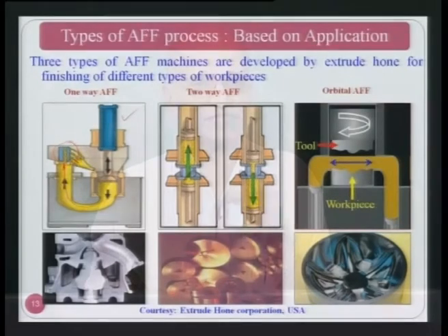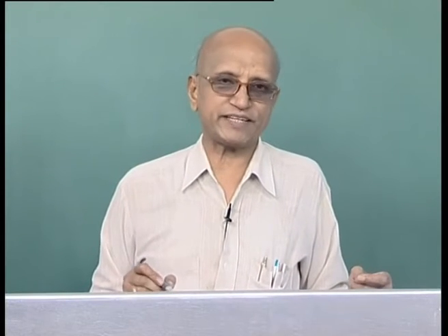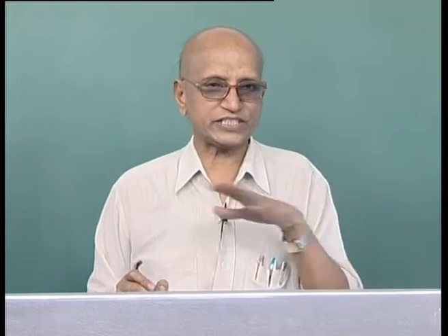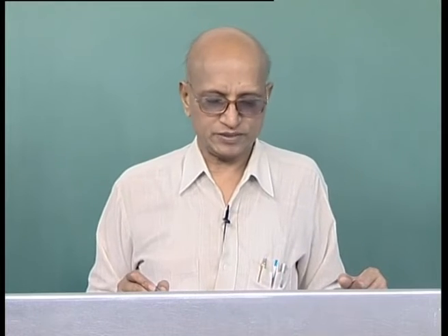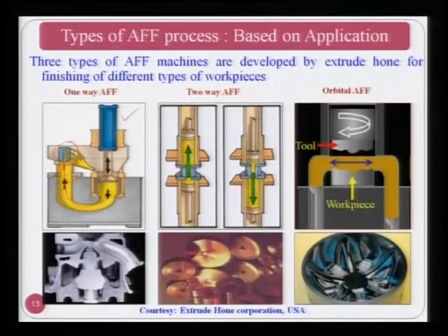is coming out and the medium consists of fine abrasive particles, these fine abrasive particles will come in contact with the workpiece surface. So, as I showed in the earlier slide, in the same way they will shear the peaks of the workpiece surface, and surface roughness will be reduced substantially. Now, after it comes out of the workpiece surface, it is collected and recirculated in the same way as shown by the arrows over here.